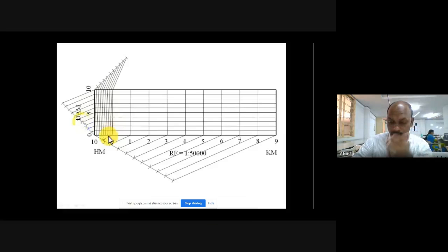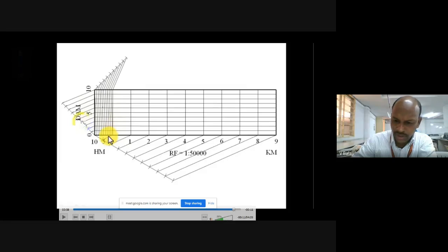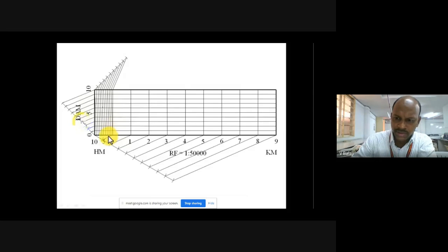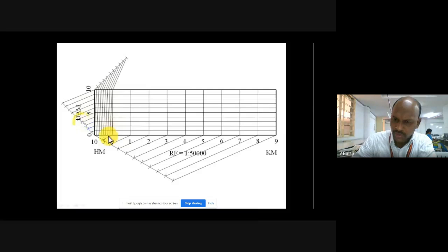You can measure 3 units with diagonal scale. Please speak louder, I am unable to hear you. Yes, simultaneously we can measure 3 units. One is the main unit, its subunit and its subunit. So 3 consecutive units we can measure.